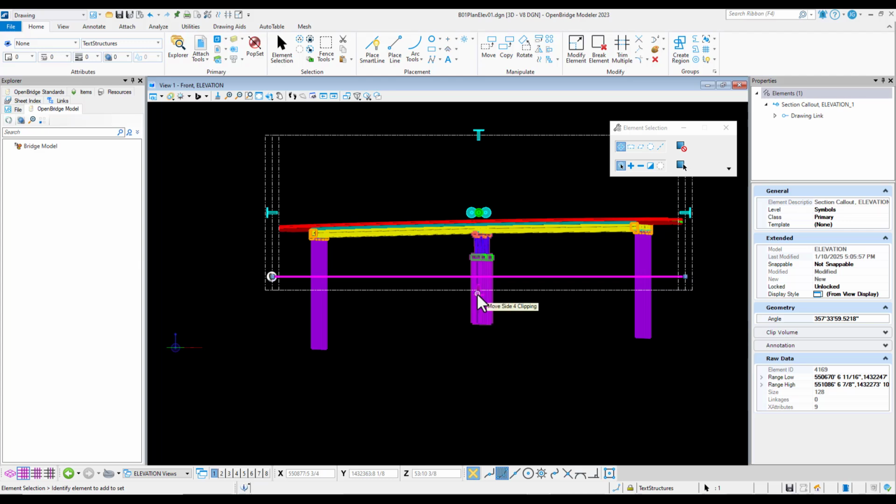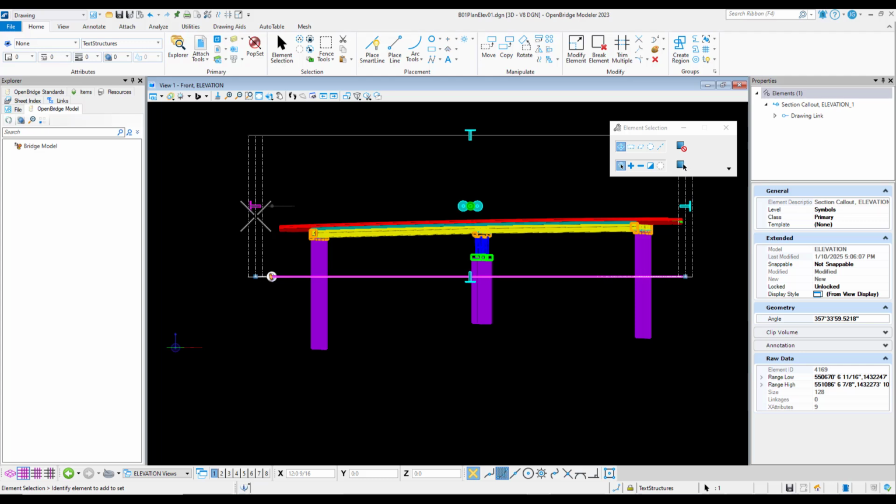So now I'll manipulate the saved view a little bit. I'll pull our handle up to the callout, and keep in mind you can update this saved view as much as you'd like. If you wanted to increase what is shown, you could always make that bigger by dragging the top and the bottom ones down. If there's more that needs to be shown on the left or right side, you could grab those handles. It's very, very easy to manipulate those.